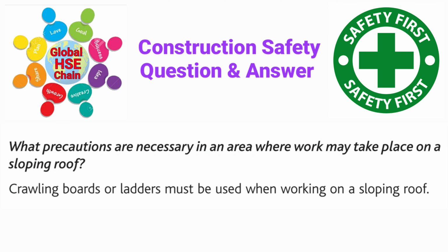Question is, what precautions are necessary in an area where work may take place on a sloping roof? The answer is crawling boards or ladders must be used when working on a sloping roof.